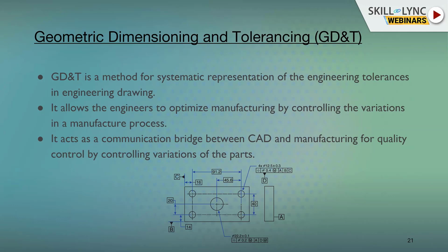Additionally, another part of GD&T deals with the fit and finish of the components, where the gap between those components is determined, like how much gap should be maintained between them. A method called RSS, the root sum square tolerance method, is used to determine the gaps, and it also takes material properties and manufacturing tolerances into consideration. This in turn helps determine the best fit and finish of the system, which is important for the assembly.